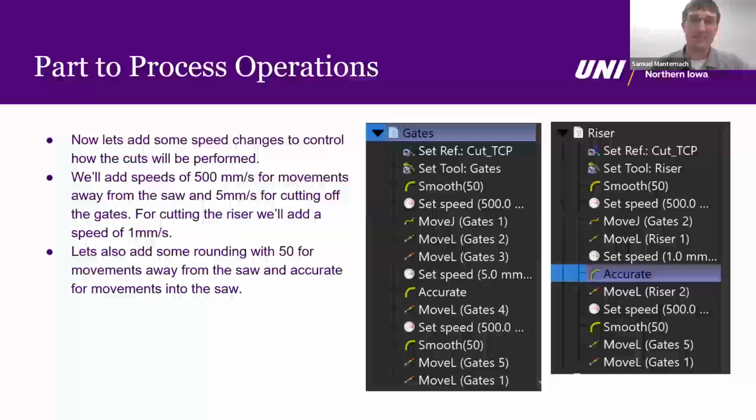Beyond that, some of the testing we've done also includes things like abrasive band or abrasive cutoff saws, which are less of a great fit for a robotic cell, simply because you have to add another layer of coding knowledge built around the ever-shrinking saw diameter. So for our case, we're using this bandsaw, which is consistently in the same location every time we're going to start cutting. All right.